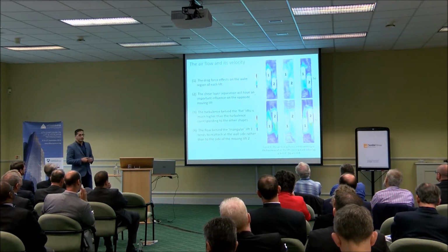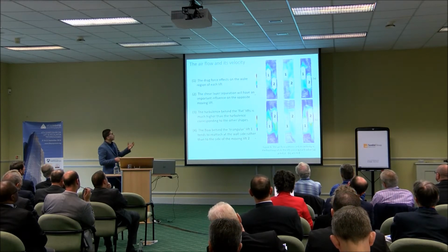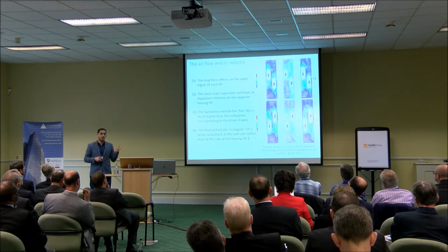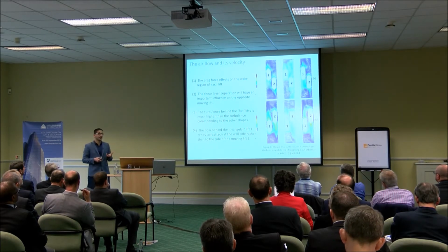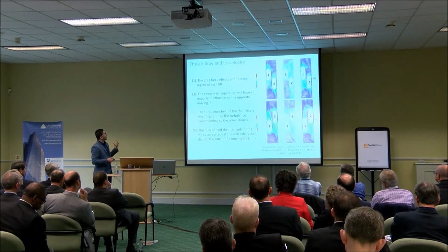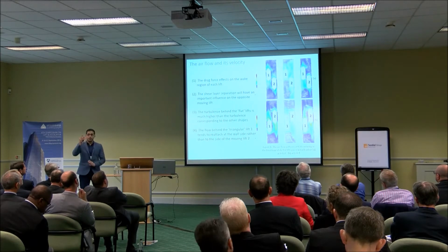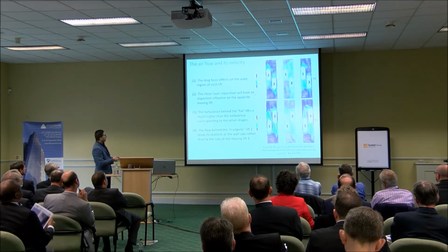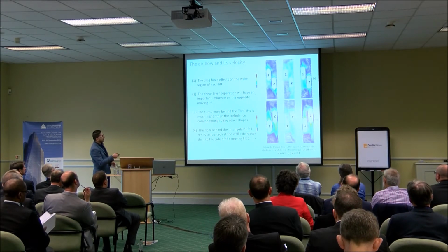The drag force has an effect on the flow in the wake region of each lift. In this kind of engineering problem, predicting and modeling the shear layer separation is very important because it will have an important influence on the opposite moving lift, because we have two lifts passing each other. This figure shows the airflow patterns and its velocities in the hoistway.